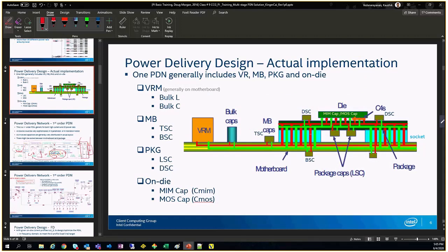So what you do is you add capacitors to act like a temporary charge storing, temporary battery. So what happens is, when it's pulling current, momentarily it will pull from here. This capacitor will provide the current. By the time this cap will charge this cap, then this cap will charge this cap, this bulk cap will charge this cap. By the time VRM will charge the bulk cap. So just for that few nanoseconds before the VRM can take over, these caps help. So what happens is, this droop is there, right?